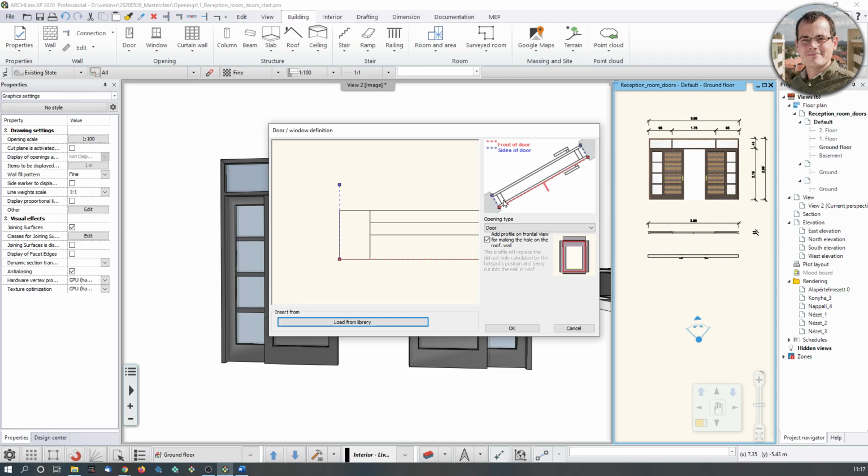These nodes are showing the insertion points of the door into the wall. So you need to align these edges with the nodes. That way the software would cut the wall exactly the right size. So if you don't have that figured out, then the result might not be that good.